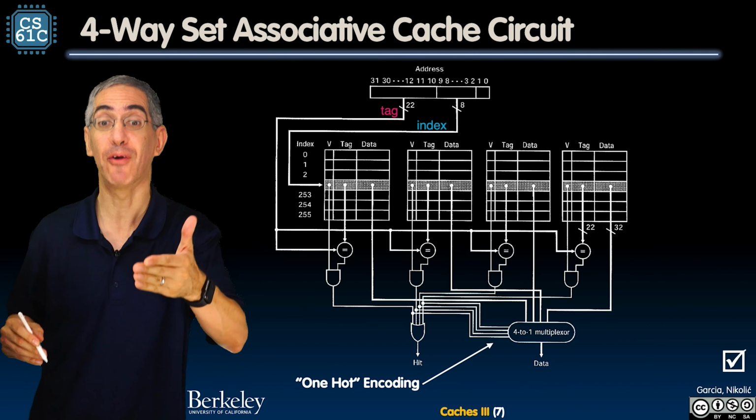This is fun. So what's happening at the bottom is, each of these is, did it match? So each of those are comparators. Does a tag match and is it valid? Because, remember, don't forget the valid bit. You could have garbage there that happens to match the tag. That would be really uncool. Now, do I have a hit? Sure, it's an OR of all 4 of those lines. So that makes sense. Now here's the interesting thing.